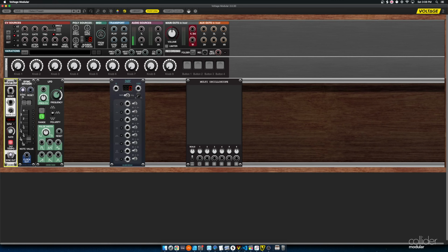All right, so starting out here, getting this wired up, you can see I've got a sync generator and a sync divider off to the side, and I'm going to patch the clock signal to the clock. The clock here really represents the sampling rate of converting from analog to digital. You can make this as fast or as slow as you want, and really it depends on what you're doing. You'll see that as we get going here.